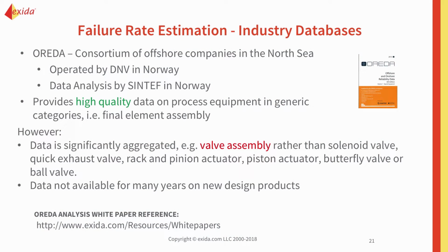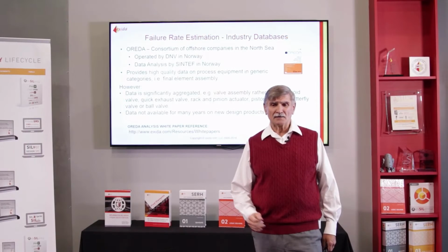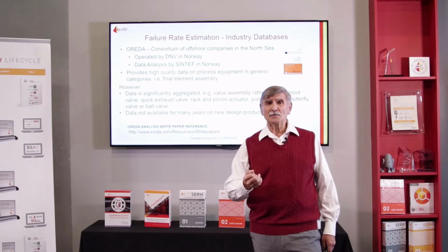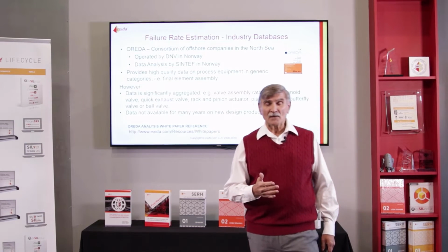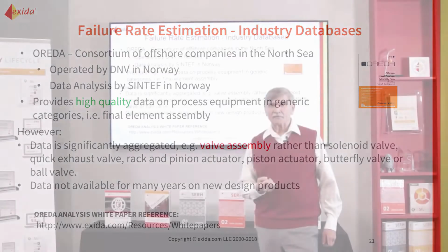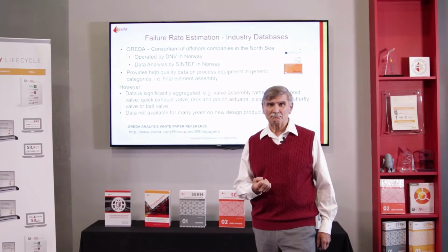Industry databases. Consortiums exist in the process industries. The OREDA database, the Offshore Reliability Equipment Database Association, gathers up failure data from offshore platforms in the North Sea. A number of different companies supply this data. It's sent to Trondheim University, a company called SINTEF, which has a large group of experts, and they are producing very high quality data for the process industries. I can't thank them enough.